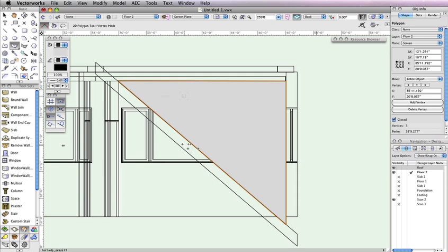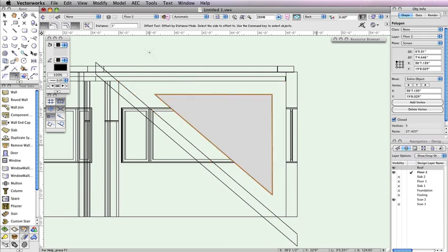Once the triangle is completed, select the Offset tool from the basic tool palette and enable the mode Offset by Distance and Offset Original Object in the toolbar. Also in the toolbar, set the distance field to 1 foot. After that, click inside the existing triangle to create a smaller offset of the original.